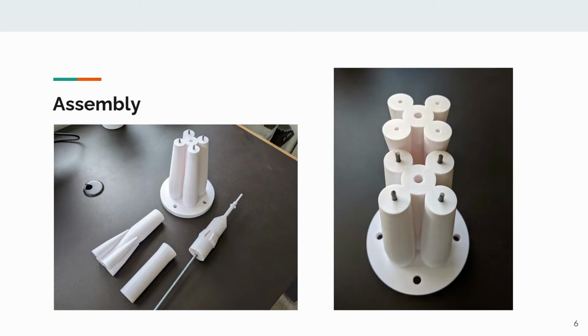As for the rocket itself, it was printed in 4 segments. This was done in order to maximize the overall assembled height of the model. However, this of course brings into question the method of assembly and any idiosyncrasies that may arise from having a non-singular print. In order to tackle the issue of assembly, the team decided to adhere a threaded rod within the top segment of the rocket, which would pass through the center hole of each piece.